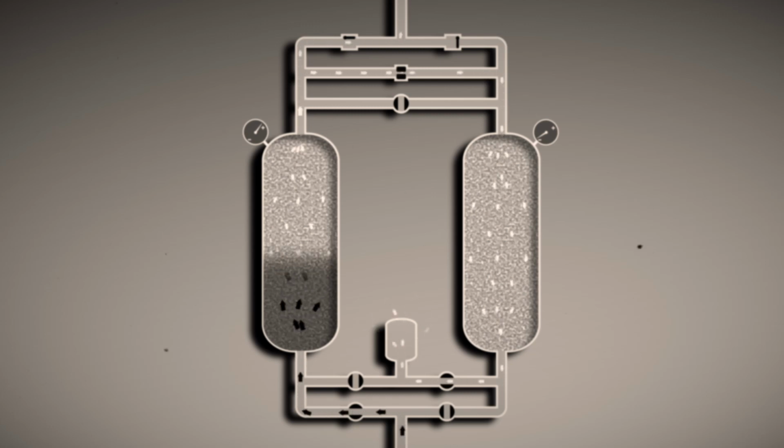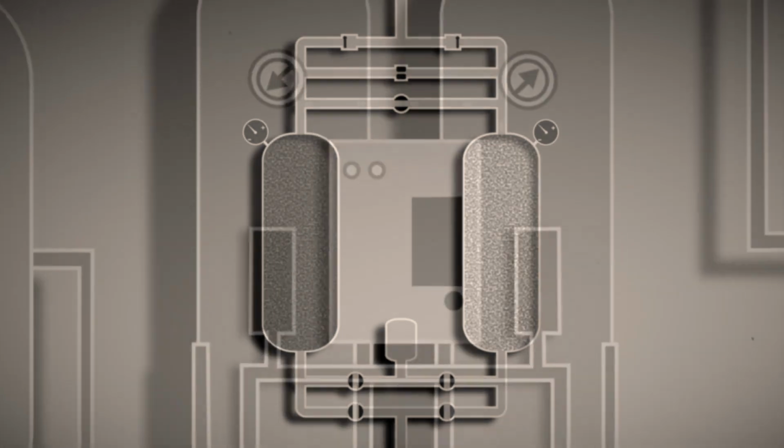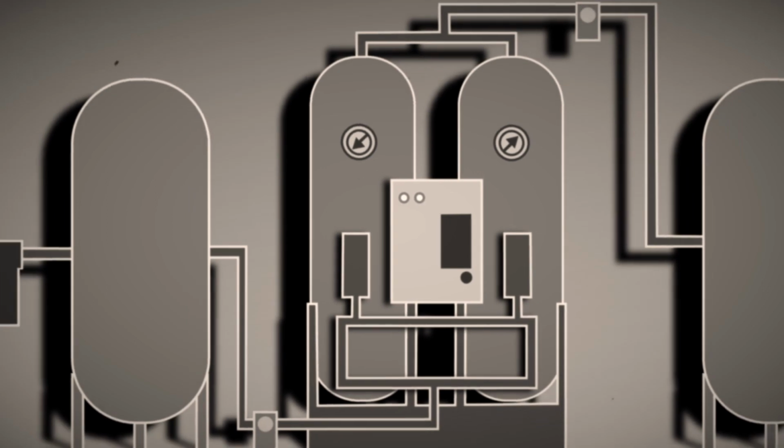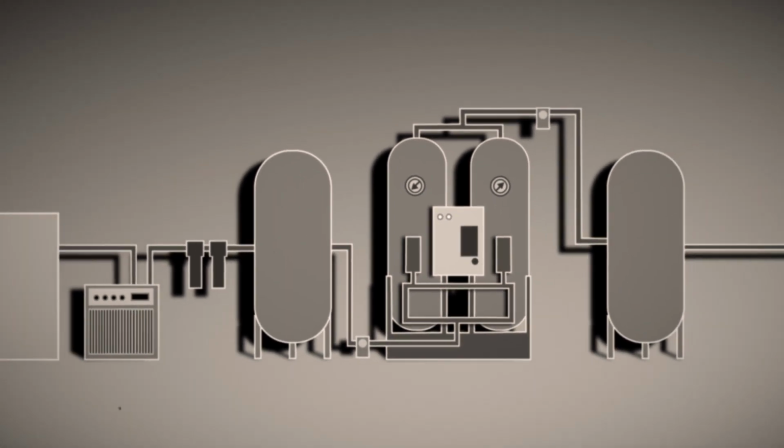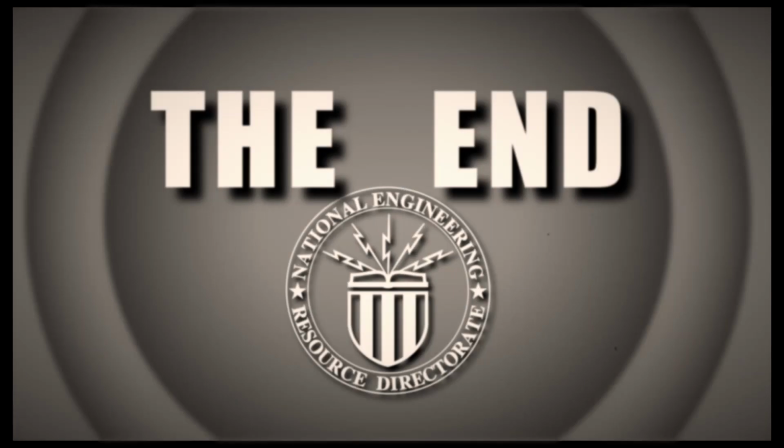The pressure in the right sieve bed has fallen, while the pressure in the left sieve bed is rising. When the left sieve bed is almost completely saturated, the left feed and right exhaust valves are closed. Again, we equalize the sieve beds, helping to begin production on the right sieve bed. Through the pressure swing adsorption cycle, precious oxygen can be made from compressed air and distributed to patients in need.